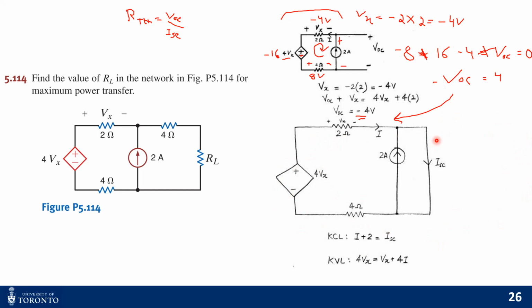Now, if you see, this wire short circuits the entire circuit, right? So the 2 ampere source, ideally it should split on the left and on the right, right? But since now the entire 2 ampere is short circuited, the entire 2 ampere flows into this loop, and no current goes on the left hand side of the circuit, because the short circuit has the lowest resistance, so the entire current will be flowing like this.